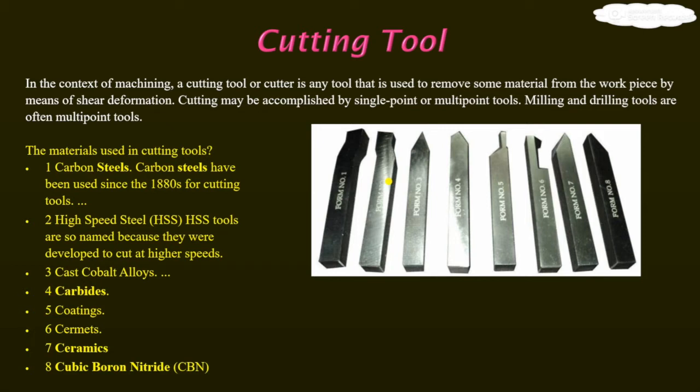Why is it required? During the cutting operation, the tool gets heated, and it is expected that at that high temperature the strength will remain, sufficient hardness will remain there. So hardness at high temperature is also another property to consider while selecting the cutting tool material.